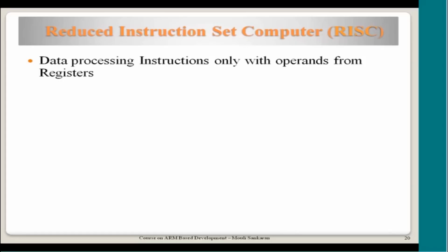Suppose the maximum physical addressing capability of the processor is 32 bit, then the 32-bit location address needs to be mentioned in the instruction to say where the other operand is coming from in memory. So basically, when you have operands coming from memory, we need more bits in the instruction to mention where this operand is coming from. Because of this, our decoding logic also increases and our instruction bits also change based on the operand.